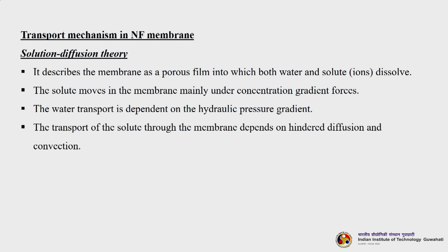So, under solution diffusion, this we have discussed in detail earlier. It is the same as for RO. It describes the membrane as a porous film into which both water and solute ions dissolve. Whatever water is getting through has to be sorbed inside the membrane material, and only then will it get to the permeate side. Similarly, the solute ions which are supposed to be transmitted through the membrane must dissolve in the membrane material. Then diffusion will take place.